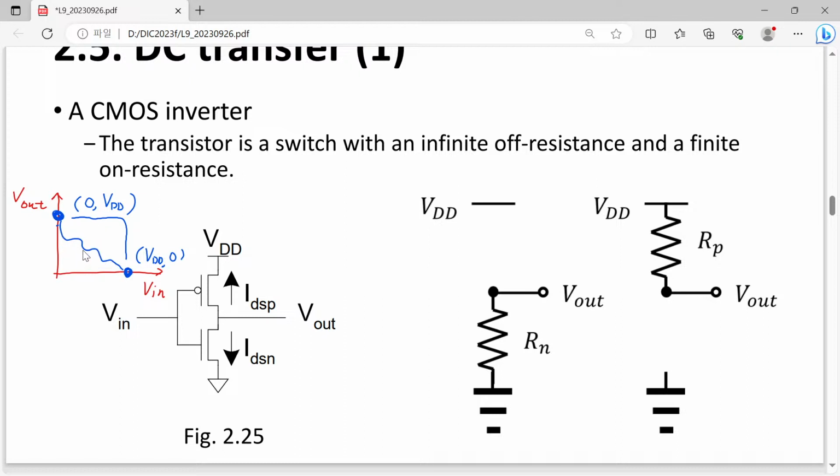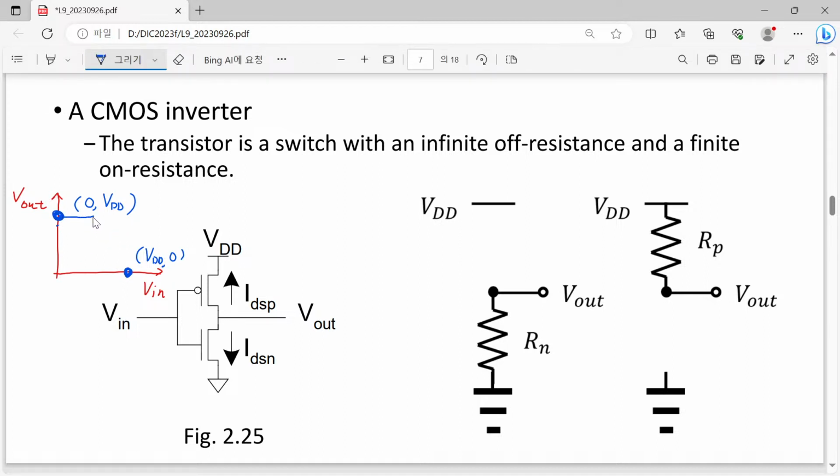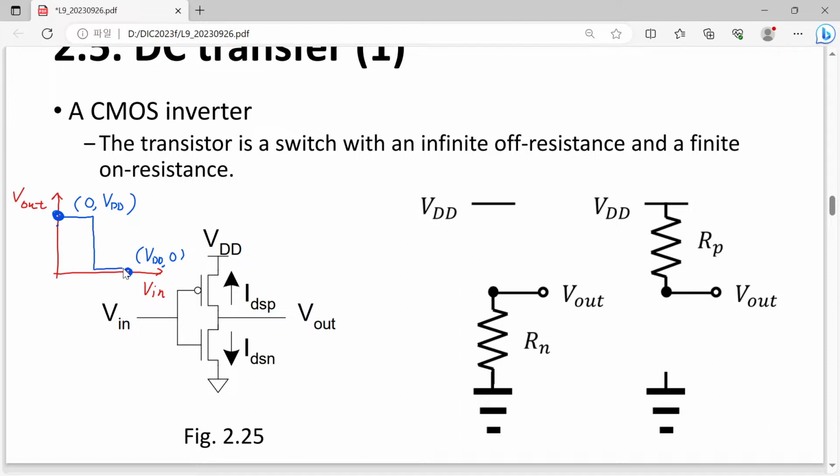Of course, in this CMOS inverter, the ideal shape would be like this. Maybe this is the ideal one. Sorry about this small difference, but you know, this is just attached to exactly 0. So up to here, maybe preferably about half VDD, that is just regarded as a logical low, and beyond that value, that is regarded as a logical high. That would be quite a good situation.